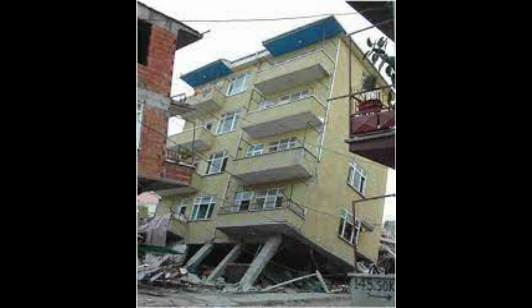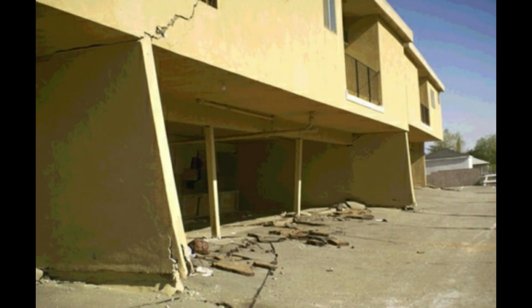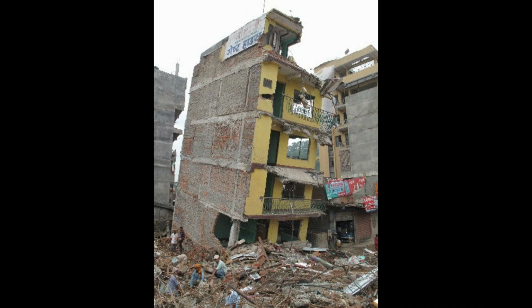This lack of stiffness can lead to local or even total building collapse during seismic events, putting lives at serious risk. While it's best to avoid soft stories, if one exists in your design, a dynamic analysis according to the UBC code is absolutely necessary to ensure safety.